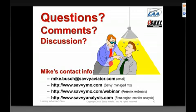But if the weather is below standard atmosphere, then I would lower the target CHT by the amount that the OAT is below standard. Most of the time we're at standard atmosphere or above, so it's not something we have to worry about most of the time. But if it's particularly cold out, then it's worth worrying about.